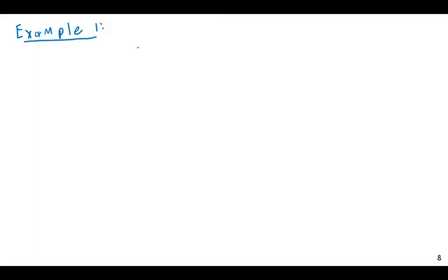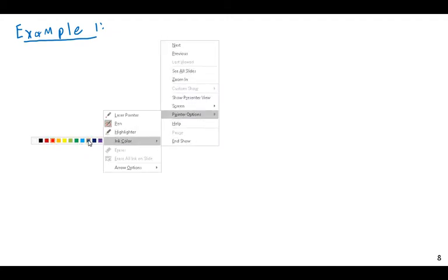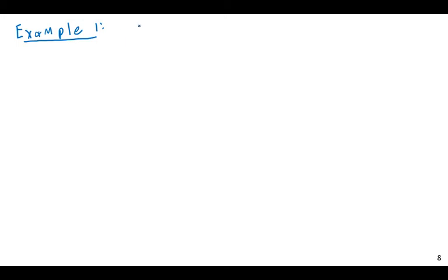Okay. So, I'm going to be given a certain cross-section, and let me illustrate this, and I'm also given some other information. Let me give you that information first. I am given that this has a V, another shear load, of 50 kips, an I of 136 inches to the fourth, and a Y bar of 5 inches for the neutral axis.